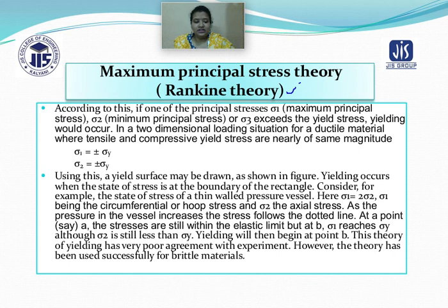So, sigma suffix e is none other than the stress at the elastic limit in a uniaxial tension test, and sigma y, if you consider, is your yielding stress. And the most important point is that this theory basically holds, or is found to be, a reasonable way to deal with brittle material. Okay. So here you can see that the maximum principal stress theory holds a good position for your brittle material, more than any other material.